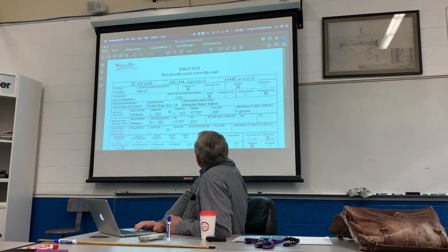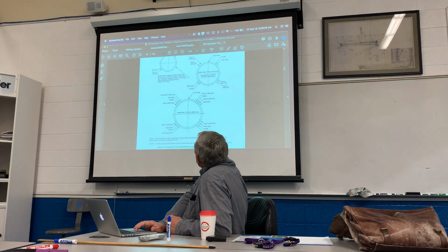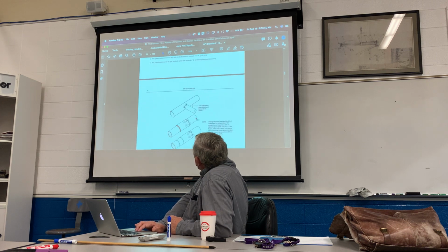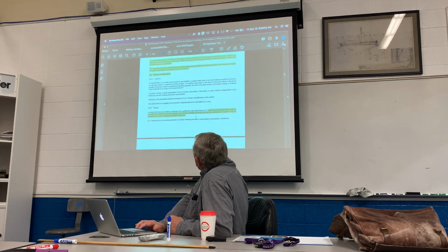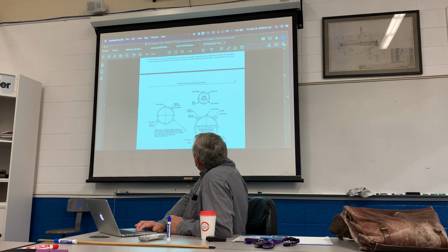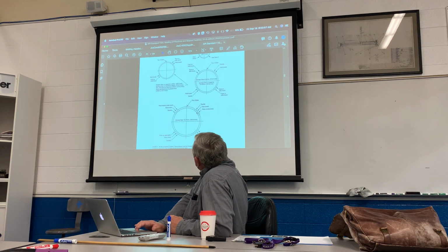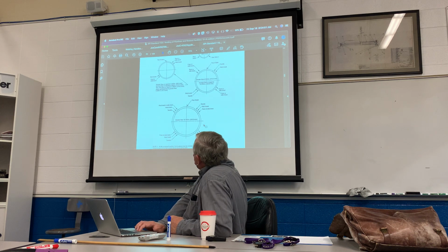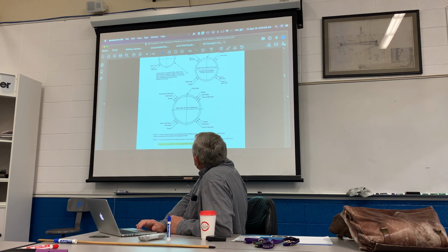Okay? All right, back to this one. So now you can see these 4 on the procedure qualification test, and then if you go back down to the welder qualification, you'll see the same thing here, right there. Now I only have 3. See that? For the welder qualification test, you have